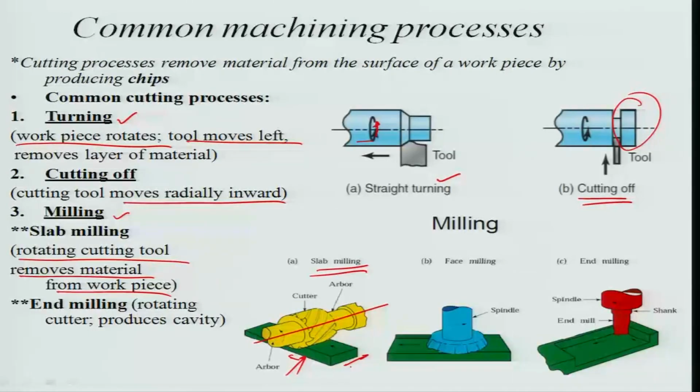You can also have different other forms of milling, like the face milling example that I was providing, where the cutting motion is also along a circular plane, which is probably in the similar direction. So the cutting velocity, for example, in this particular direction is similar to that of the feed motion, or is similar again to the direction of the feed motion of the tool in the y direction. So in these particular examples you can have a planar surface.